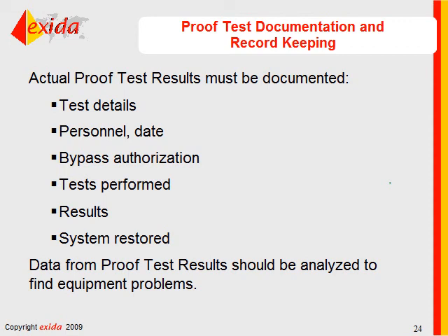Then one other aspect, and this is where the different schools of thought show up, but the objective of the proof test is to detect undetected failures. And manufacturers know what those undetected failures are. They know their product. So if you look at the internals of a transmitter, there's nobody other than the manufacturer that can actually tell you what those failures are.